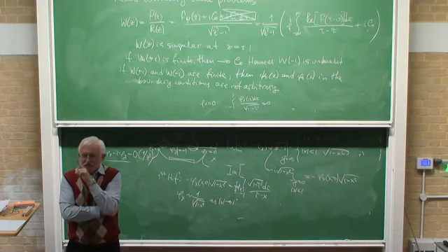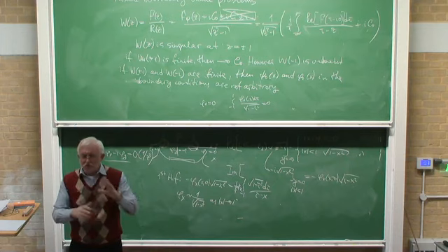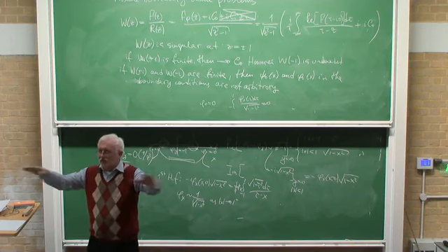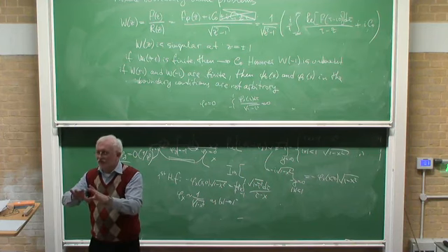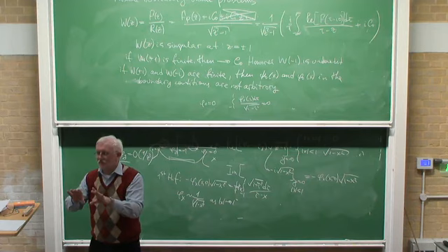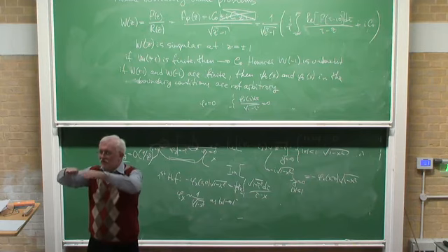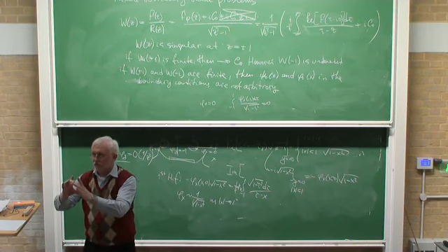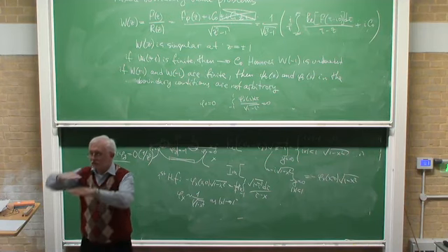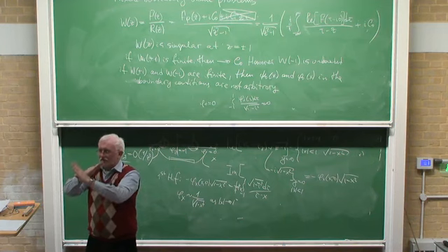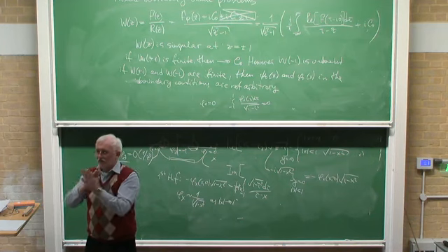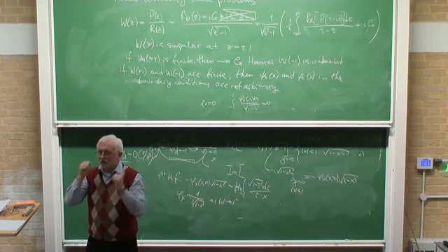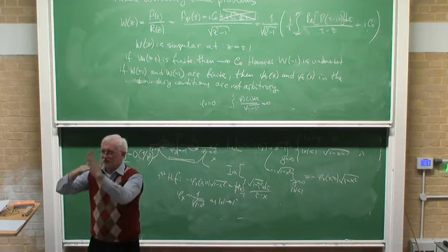If it's a free surface and submerged bodies, the conditions are not a mixed boundary value problem. On the free surface there is one condition, on the body another condition, but these boundaries do not intersect. So this is only for floating bodies, where there is that contact point.